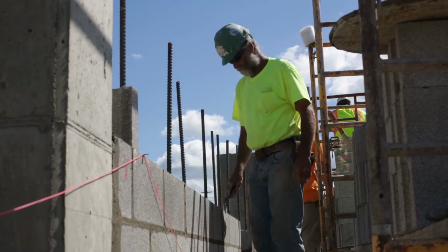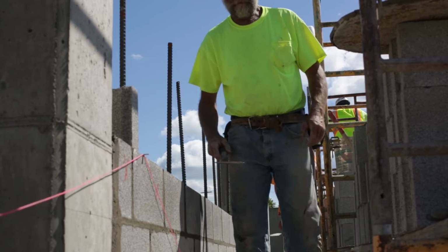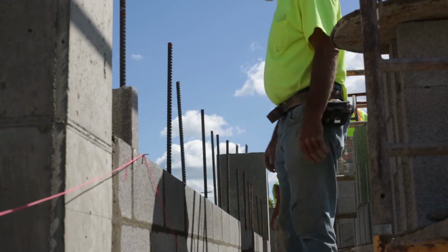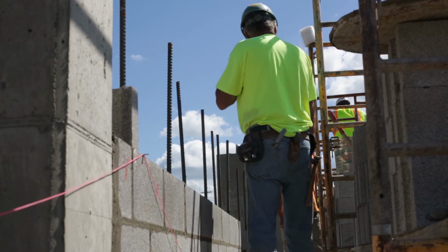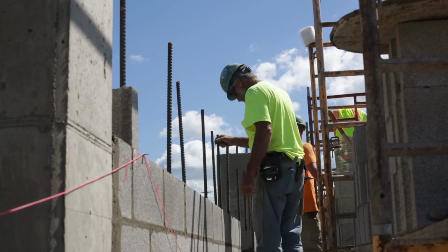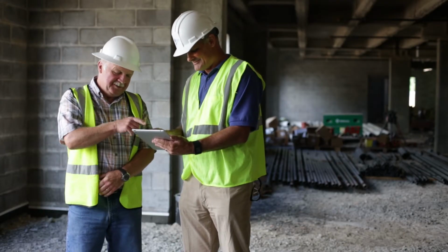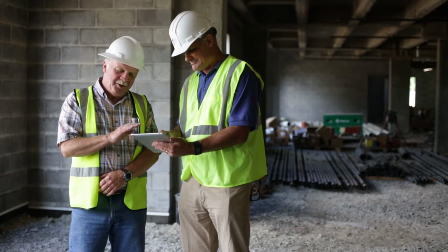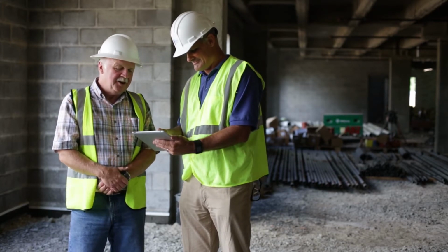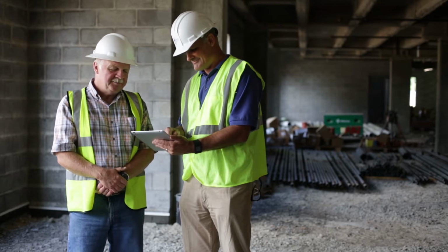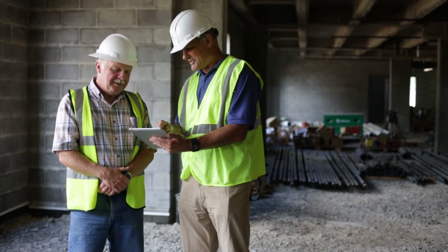In the field, it is possible that you may encounter situations where your training has told you that an area that flashing is typically required by code has none designed. It is important to alert your foreman and employer whether a drawing or specification should be reviewed with the designers to avoid future moisture-related problems.